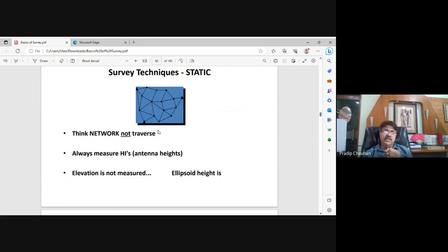And for the area of the triangle, where you need not go for the base and perpendicular height, straight away take the perimeter divided by 2. That is A plus B plus C, the three sides of the triangle, divided by 2. So it's the semi-perimeter. Let's say it is S. And your formulation is under root of S into bracket S minus A, bracket S minus B, bracket S minus C. So the square root thereof will give you the area of that triangle. And thereby they were measuring, and all those projects were executed using chain and compass.